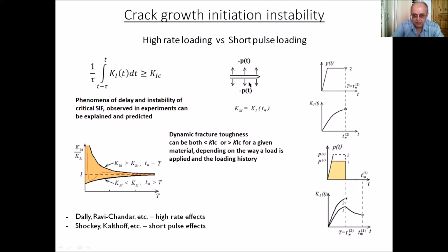If we solve an elastodynamic boundary problem, and utilize then incubation time coupled with this dynamic solution, then we can get some very interesting effects. You can get the effect of unstable behavior of K1D at the start of crack growth. The principal nature of such instability is related to the difference between high rate and short pulse loading. So high rate loading and short pulse loading are principally different.